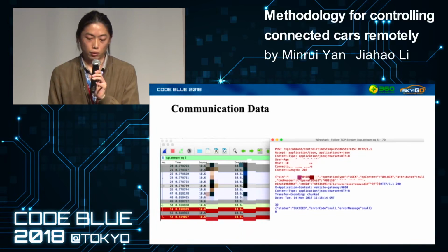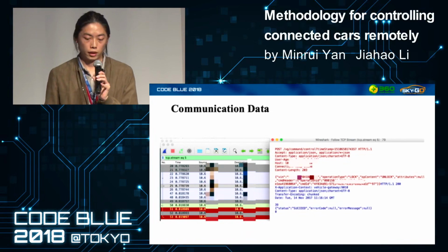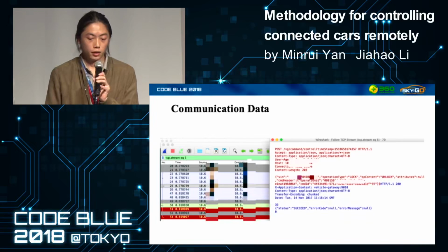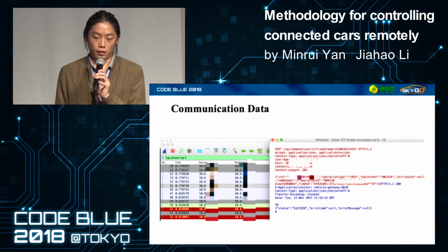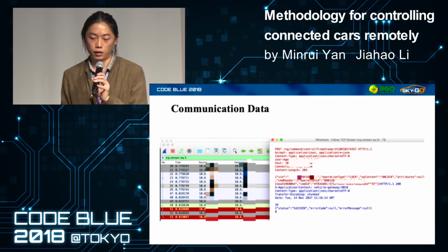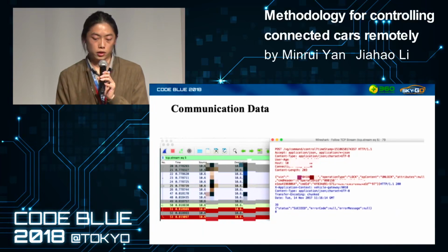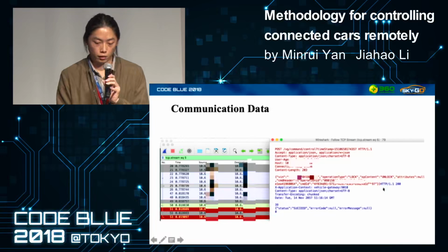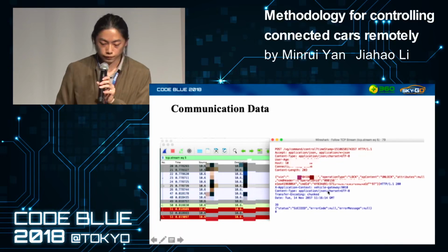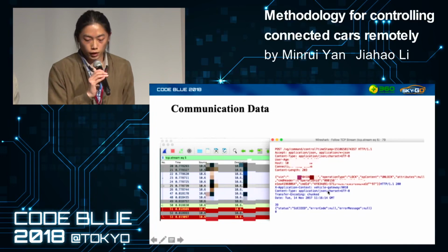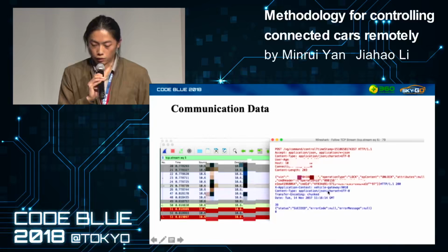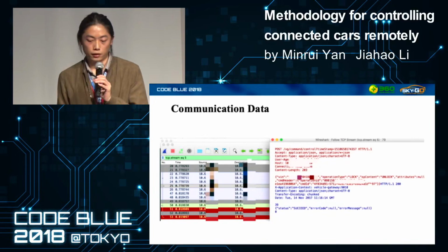We send a command to our car, then capture the corresponding payloads by Wireshark. And we found all the command names. The command server sends commands to the vehicle gateway with tokens. The tokens are the operation ID and the CMD ID. We call it command ID. In this picture, you can see CMD ID in the right window. The operation ID is fixed by specific car versions. The command ID is the real token generated by the data center.